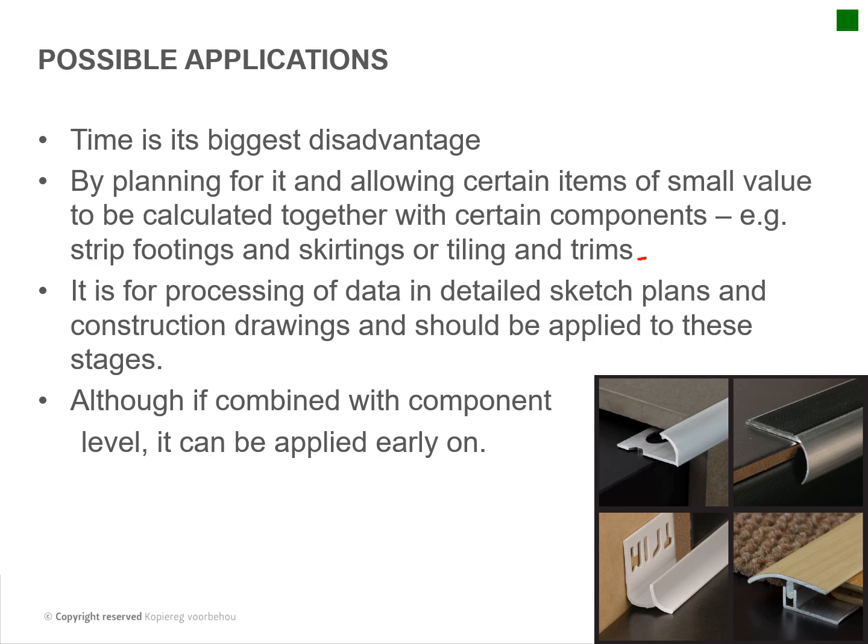And then from that you actually have most of the specifications already with the costs available. So you can actually do elemental estimation very early on. It just means that the design area falls a little bit more towards the QS to actually assist with the design of the types of finishes.